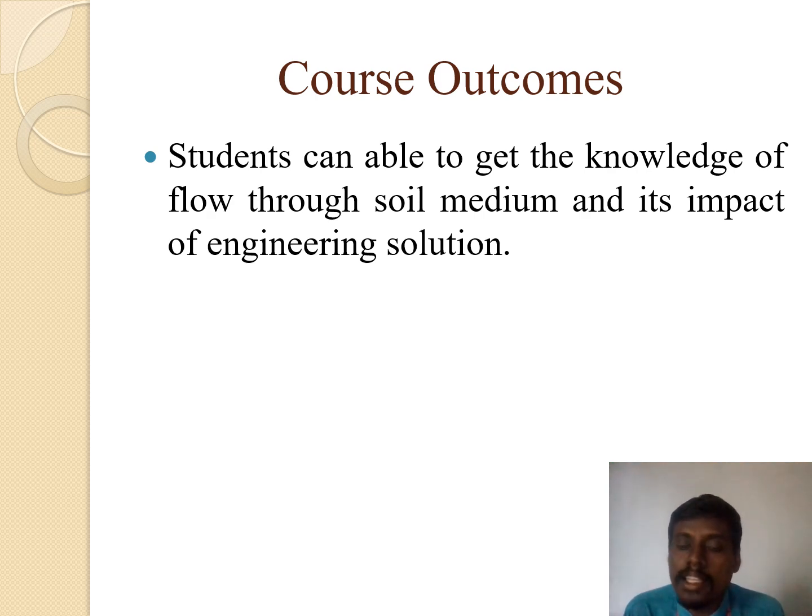The next important thing is how to find the coefficient of permeability. There are two tests: the constant head permeability test and the falling head permeability test, and the pumping out test is also carried out in the field. For unconfined and confined aquifers, the pumping tests are carried out, and the coefficient of permeability is found. And next we discussed the two-dimensional flow as well as the Laplace equation,